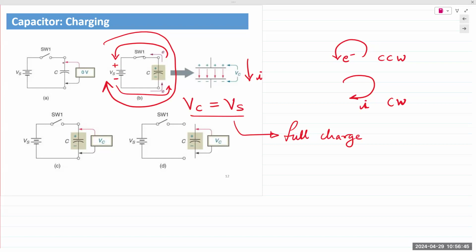So we would think that the capacitors, electrons are flowing through the circuit, and I stated, right? Electrons are flowing through the circuit, and I said current would flow through the circuit. And this is the important point. This is exactly the reason why I would say leave the physics on the side and think only in terms of electric circuit analysis. So electrons are moving in the top half of the circuit right here and the bottom half, but they do not actually flow through the capacitor itself. Because it is separated by an insulating material, it can never pass through.